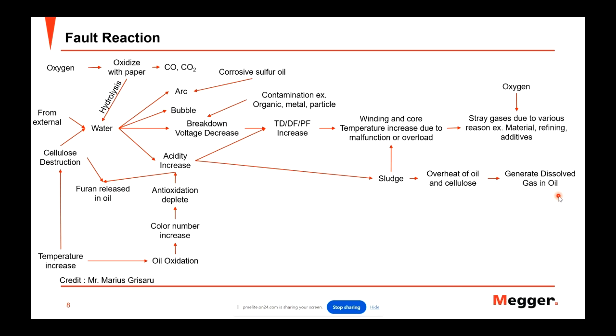Meaning, if you analyze the dissolved gas inside your transformer correctly, I would like to highlight correctly, because many times we have inaccuracy because of wrong sampling. Many causes lead to errors and incorrect information that can lead to misjudgment of the dissolved gas inside of your transformer, or the DGA result. So actually DGA is a very, very excellent tool to analyze your transformer.